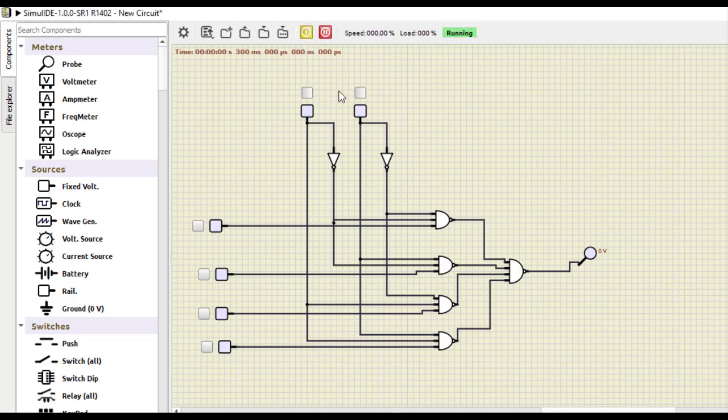We just turn it on. The select lines are 0 0. For 0 0, if we turn this on, for 1 we are getting 1 output, and for 0 we are getting 0. Out of these 4, if I turn the others on and off, it won't have any effect on the output. These 3 are not selected, but this one is selected for 0 0.